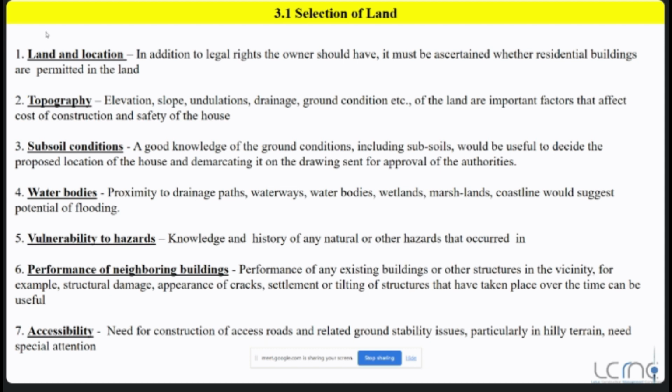Normally, keep that in mind. The general norm is 200 kilopascal as the bearing capacity, which is the safest margin. If your soil bearing capacity is low compared to the marginal value, which is 200 kilopascal, definitely you might have to do ground improvement. So that is that. I'm just stopping at that level. Otherwise, I need to explain so many geotechnical parameters. Then the water bodies.